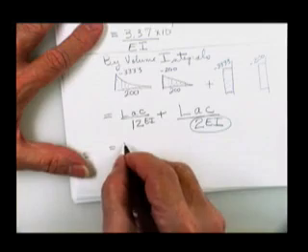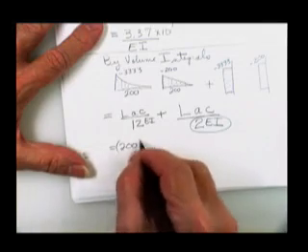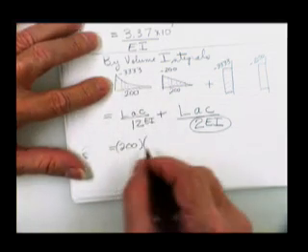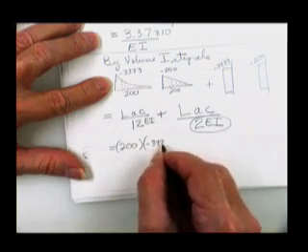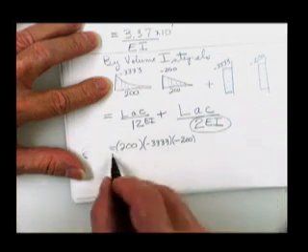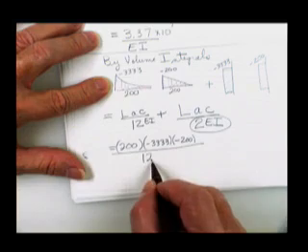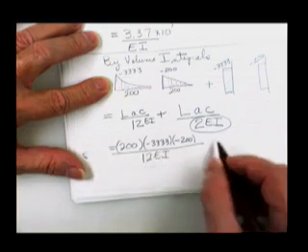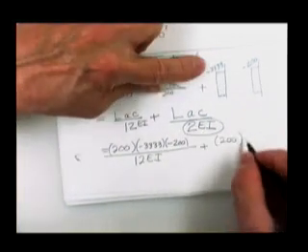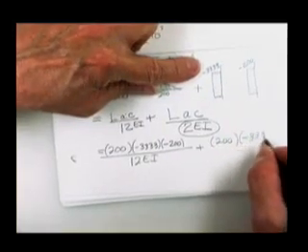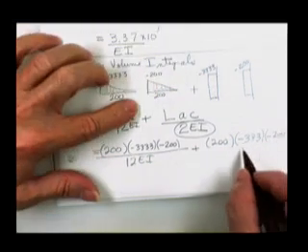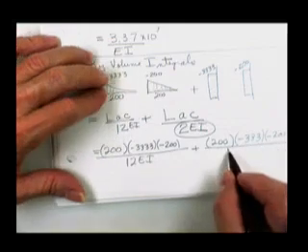So it's equal to, the length is 200. A is, well, I don't know which one's A, doesn't matter, they're both multiplied together. So minus 3333 times A minus 200 divided by 12EI, added to 200 times A minus 3333 times A minus 200 divided by 2EI.